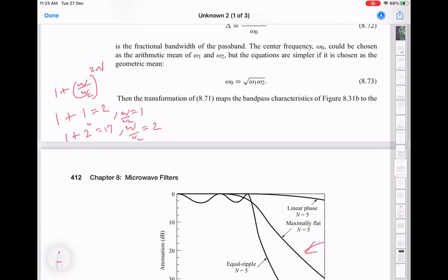And you basically say that if you double the frequency, the loss will increase by a certain amount. Or in log units, you'll say dBs per octave. You'll say 10 dB per octave. That means that every time you double the frequency, the loss will increase by 10 dB. If you look at it on a linear frequency scale, you will see that the 1 gigahertz filter will look sharper, just because it falls rapidly over 1 gigahertz. But that same drop will happen over 10 gigahertz when you have the cutoff frequency as 10. So that's what I was trying to say. Is that clear?